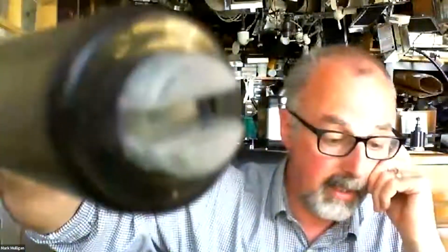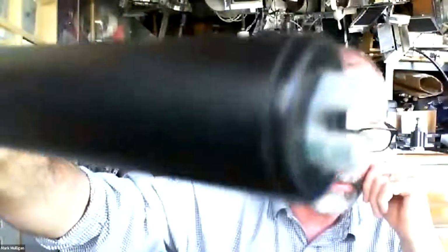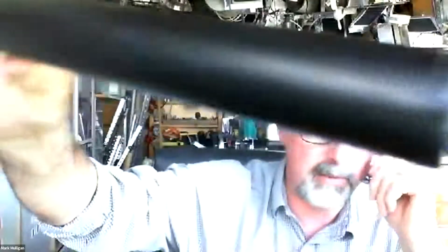This is what I mentioned, the washing machine component. Most washing machines have one of these in. It's a turbidity sensor. The washing machine knows when to stop washing because the water is clean by measuring this sensor. It costs a few pounds, and we put it in water, connect it, and that tells us the turbidity, so the concentration of particulates in the water, which is a useful measure of water quality alongside salinity and temperature, which tells us something useful biologically about the water.